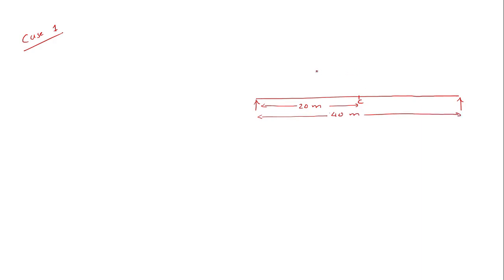Now you have the train of loads in such a way that the resultant is at a mid distance between R and 100. Then you have the rest of the loads like this, 50 kilonewton. So the value of R will be equal to 350, the sum of all these loads, and you know this distance. The total distance is 3.857.